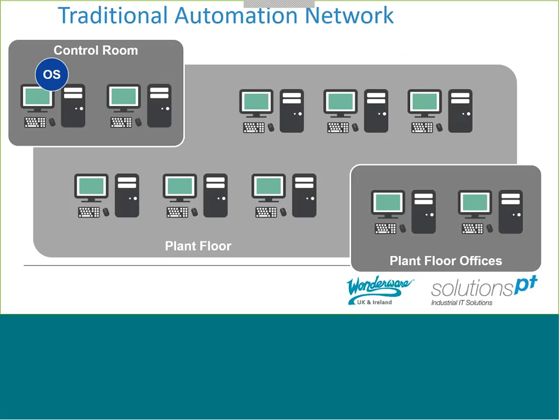So on those PCs, what have we got? We've got an operating system that needs to be at the right sort of patch level, the right version. So that lives on there. We've also got your applications, so each one might have an InTouch application on there. You might want one to be at version 10.1, you might want some at 2014 R2, 2017, whatever it is. So they need to be at the right version.